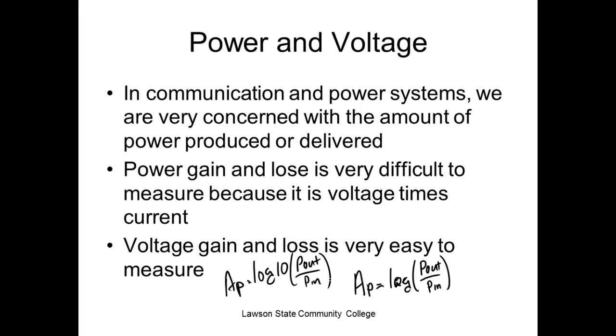What are we going to have to know? We're going to have to know the voltage and the current. I know if I've got a series resistor, I can measure the voltage drop across it and calculate the current, and use the calculated current to calculate the power. And we've been doing that a lot this class, right?